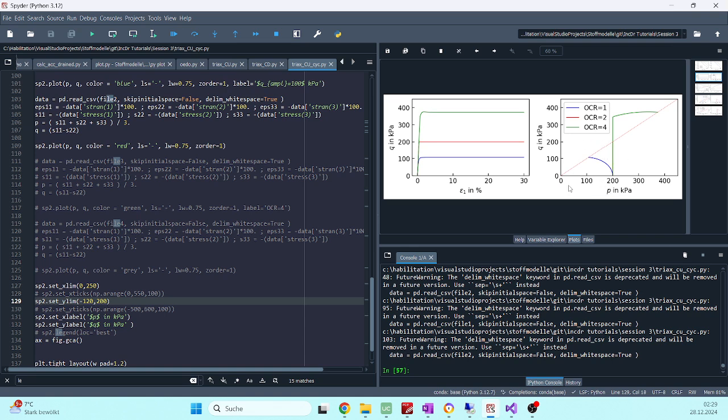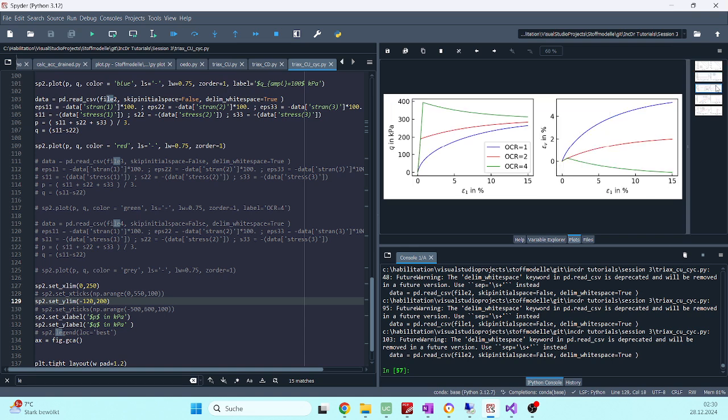And what we also know here is that the yield surface of modified Cam-clay will intersect the critical state line at PC divided by 2, which means here, or at PC divided by 2 here, because we had an overconsolidation ratio. Then the next tests that we performed were 3 drained triaxial tests with different overconsolidation ratios, changing from contractant behavior to dilatant behavior.